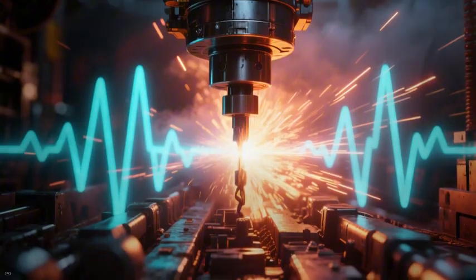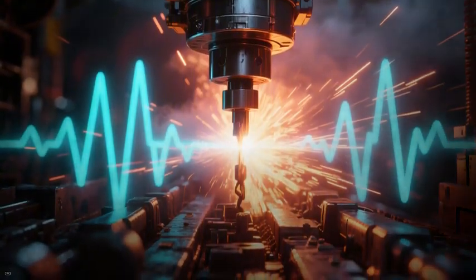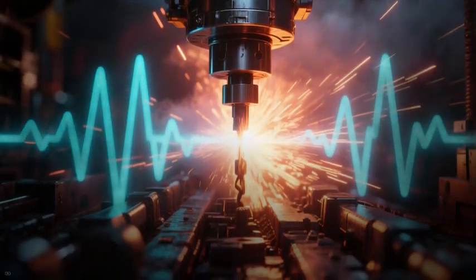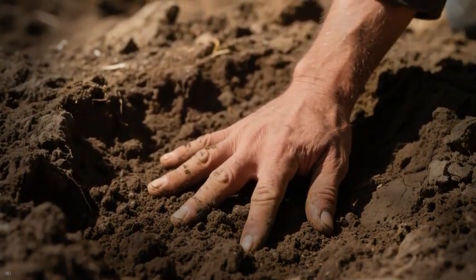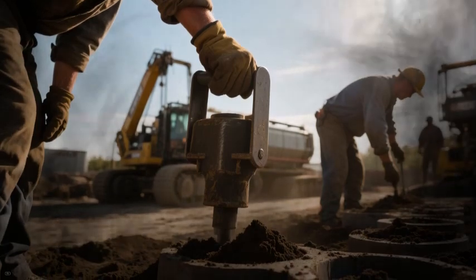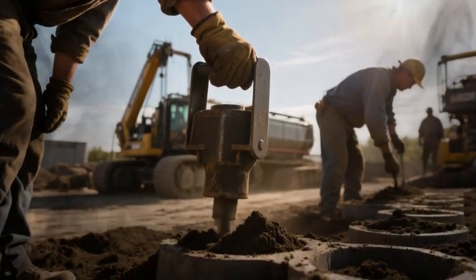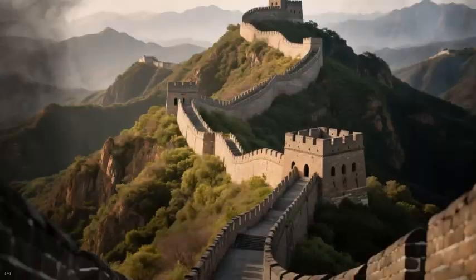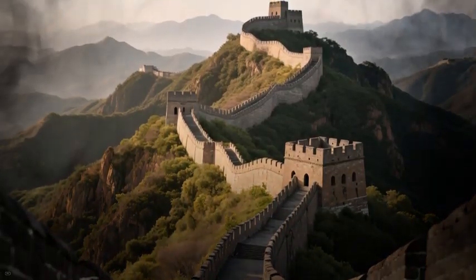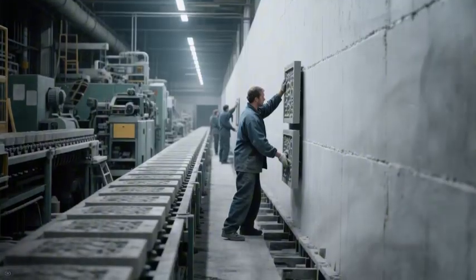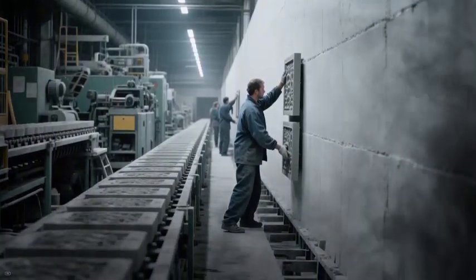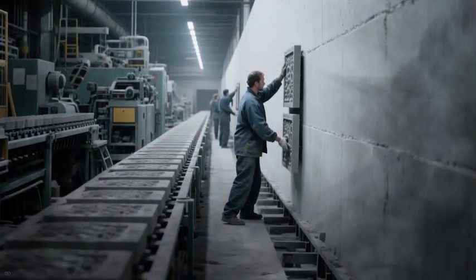Steady, rhythmic strikes compacted the earth into a dense, cohesive mass. In many cases, workers could feel the soil become harder as they continued the process. When a layer reached the desired density, more soil was added, and the process repeated. In this way, the wall grew slowly upward, layer by layer. When a section reached its full height, the molds were removed and repositioned farther along the line.